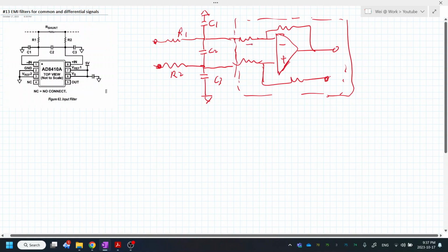It's very important to maintain the component matching among all these resistors here. And whatever resistance you add into the input filters will add to this input resistor here. Or in reality, it could be an op amp or something more complex circuitry here, but it's an equivalent resistor or equivalent input impedance. This value will add to here, okay? And this will add to the input here. And for the AC signals, the impedance of all these capacitors will also add into this input circuitry here.